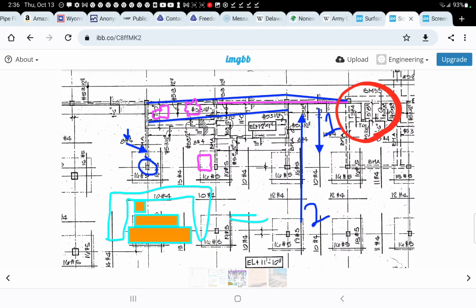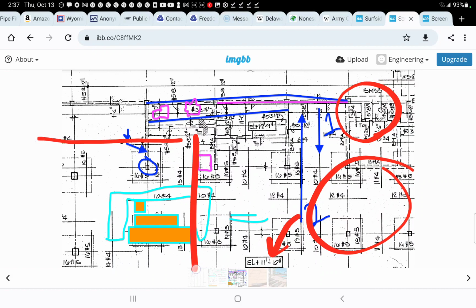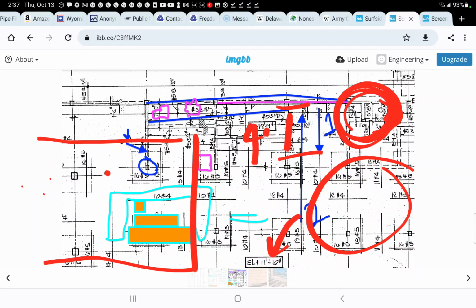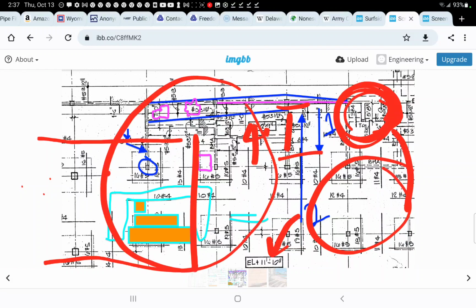This is noteworthy. When they went to 11'10" on the pool deck, remember, matching up with what I call the bridge parking deck, because it was a bridge. Cars drove underneath of it even. We also changed this from, went to 5'8". I believe this was only 4 foot 0 inches out. They extended to 5'8". That was not the initiating cause. The point is that structurally they were changing things without paying attention, obviously.